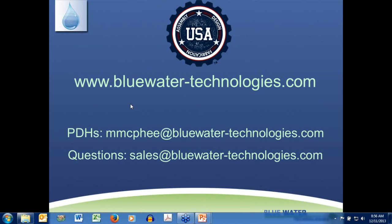I do know for sure that when you're dealing with arsenic, it's the oxidized form that you want. So it'd be the arsenate. And the reason is they just have much better, much stronger absorption properties. Their absorption isotherms are closer to neutral, and so the process parameters are much easier. So there can be some challenges with those elements if they're not in the proper oxidation state, but there are ways to overcome that with either adding an oxidation process or by reducing with some form of an acid process.